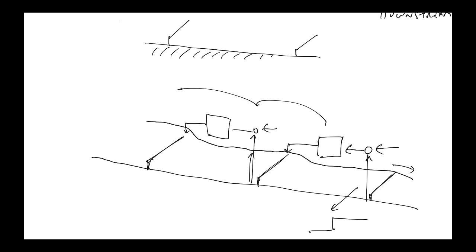So it's these decentralised controllers acting together, responding to each other's actions in a way that propagates towards the source that results in demand-driven release of water. And because we're having demand-driven release of water, you're never releasing more than is actually required, and so we can actually achieve zero outflow at the bottom. And that's where the big efficiency gains come from the perspective of water distribution efficiency.